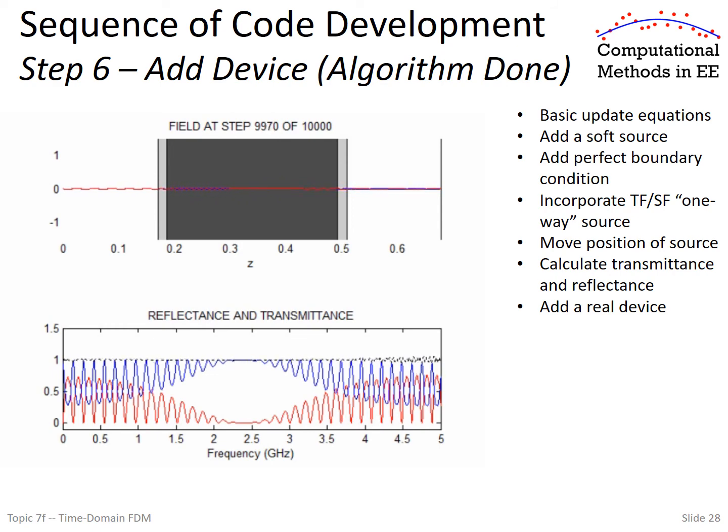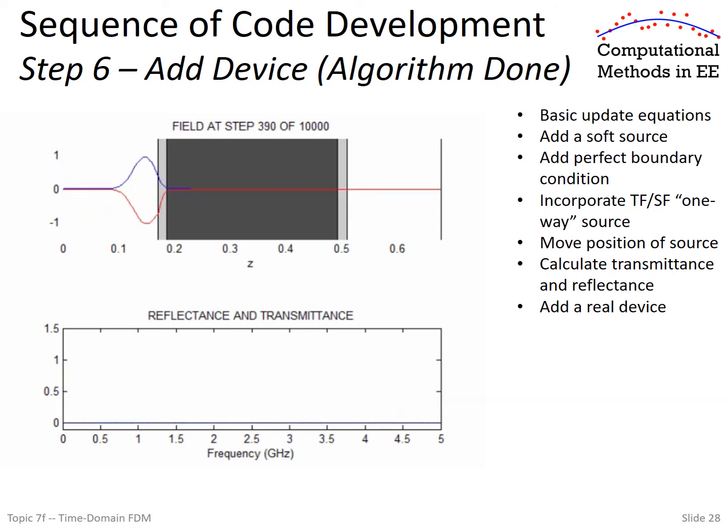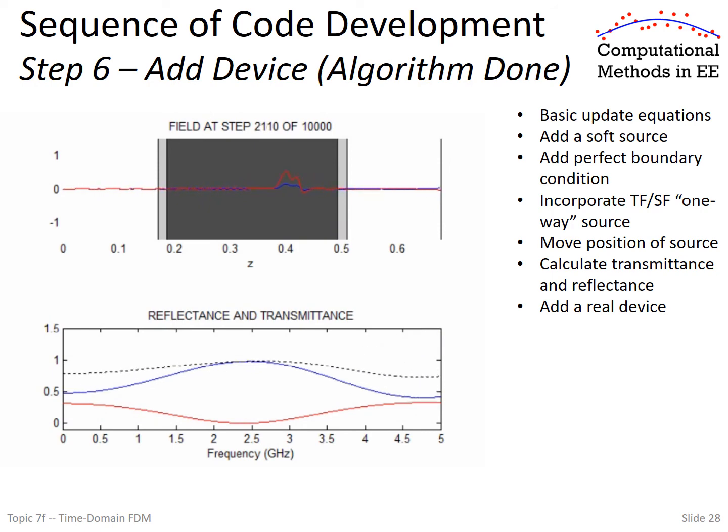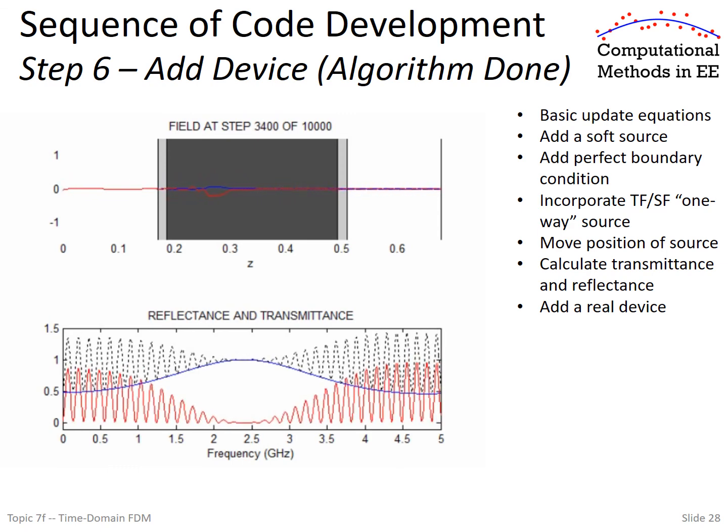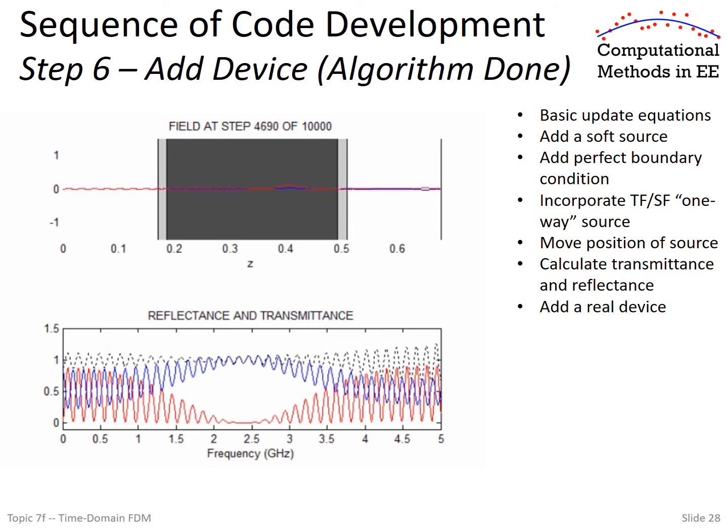This is something I always do with my personal simulations: plot that conservation line. Now clearly, if you've incorporated gain or loss into your simulation, then your conservation would not be at 100%. It would come below or above if it was loss or gain. So one thing I do in my simulations is if I want to incorporate loss or gain, I'll get everything working, I'll write my code, but I'll turn that gain or loss off. So I'll run a simulation with no loss, no gain. I'll make sure that I get my 100% conservation. Then I'll turn on the loss or gain. It's just sort of an extra level of assurance that things are right within your model.